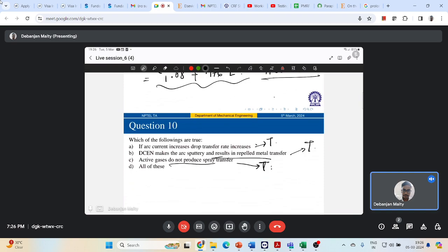You can use some kind of flux that may be used to deoxidize or clean the weld metal. Basically, if you're using flux, your flux also will melt and solidify, and it forms some kind of slag skin on the resultant weld metal. So there will be this slag formation, right, which will protect your weld pool. So you know those concepts. Now, what is there in gas welding?